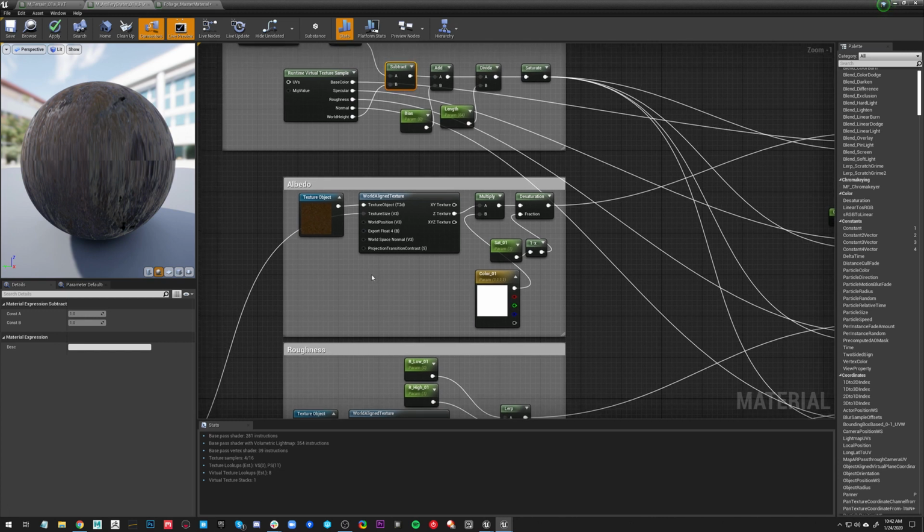It's really not great, especially because a lot of people see complicated landscape materials and they end up implementing distance-based tiling, which is really bad when you combine it with triplanar texturing because you have multiple samples for every single layer. So the more you add, the worse it gets.